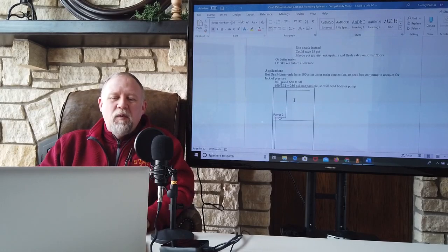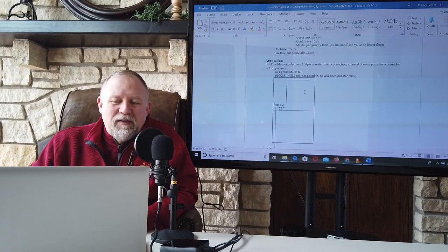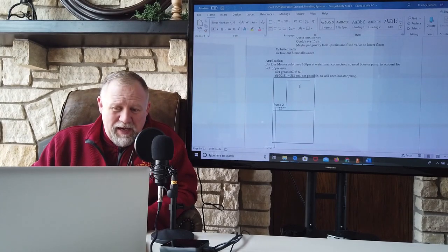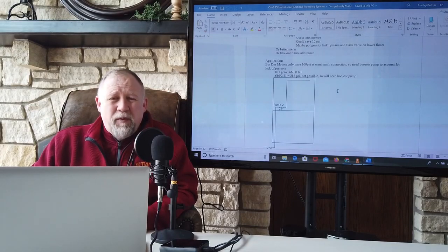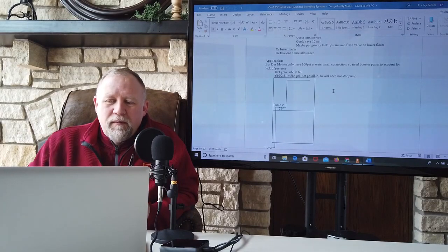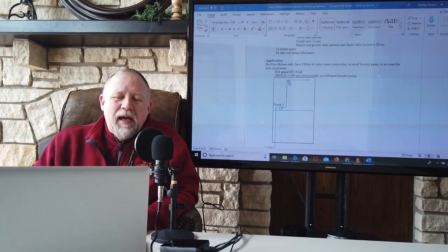All right, let's look at 801 Grand as an example. 801 Grand is 660 feet tall. That is 286 psi. No matter what we did with reduction in pressure loss for pipes or valves or backflow preventers or meters, you're never going to get there. So a building like 801 Grand would need a booster pump no matter what.